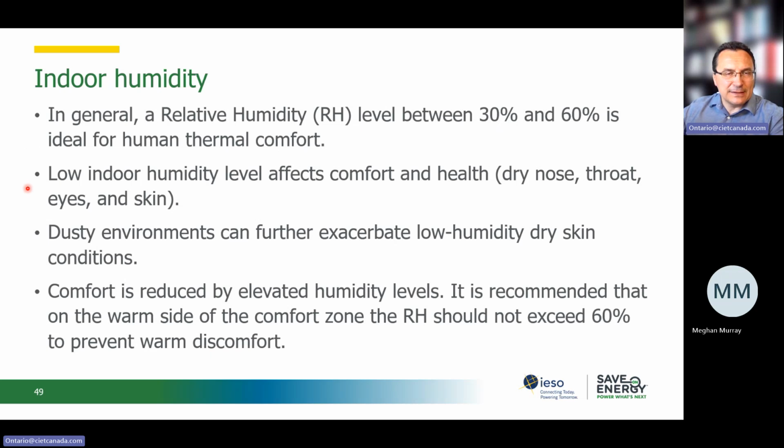What happens if we have low relative humidity in the space? Negative impacts: dry nose, throat, eyes, because of the increased evaporation of moisture from our body. We may also see, in dusty environments, the perception of low comfort in dry environments being increased. So we try to maintain a minimum of 30% relative humidity in the spaces.